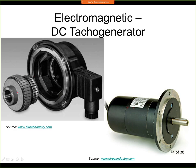Here on the left you can see a slightly different version, and we can see that there is no axis in this case. Instead, we have to push the rotor directly onto the shaft of our machine. Here you need to have the machine ready for that. You install the rotor, push it on the shaft, and then you assemble the stator like this. In both cases it will have an output voltage that is proportional to speed.